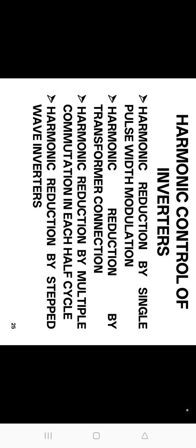The harmonic amplitudes depend upon the values of P1, P2, P3, P4 and the amplitude of VL. By proper choice of these parameters, third, fifth and seventh harmonics can be decreased considerably and the fundamental component optimized. It is noted that the three-level modulation of inverter 2 helps achieve the required stepping of the resultant output voltage waveform.